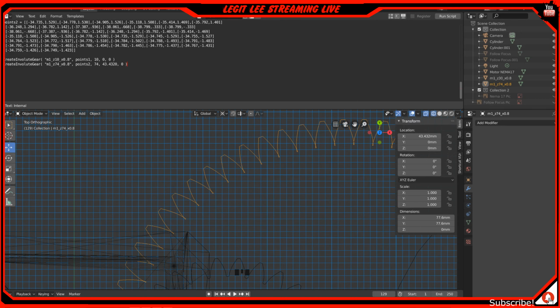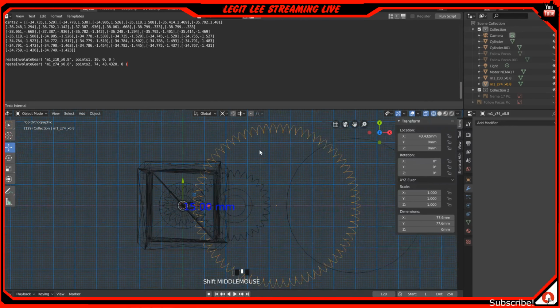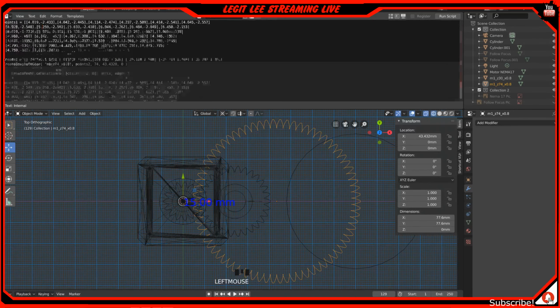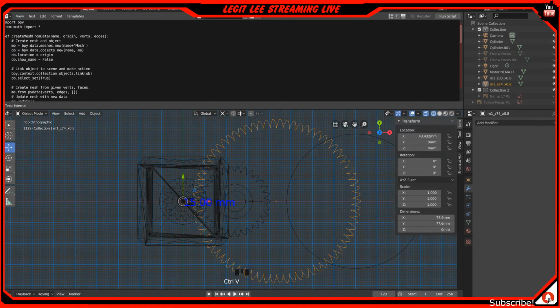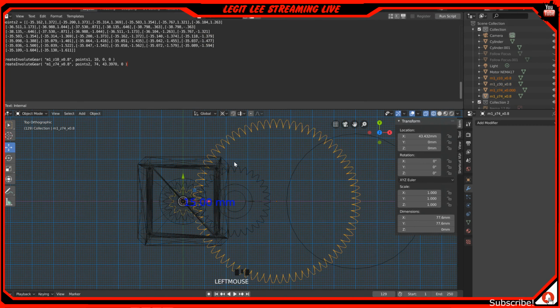So I think we're going to have to bring that pressure angle down a little bit. I'm not really liking that, to be honest with you guys, but we're going to have to, because I think we have too many teeth for it to do what we want. So we'll try doing 18, see if that pressure angle is good. Generate, copy that. Let's just generate the G code, see if it works. Paste, paste, there we go. Click that.